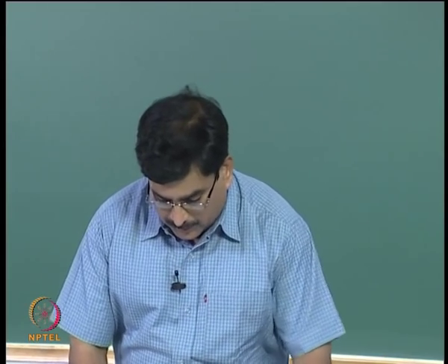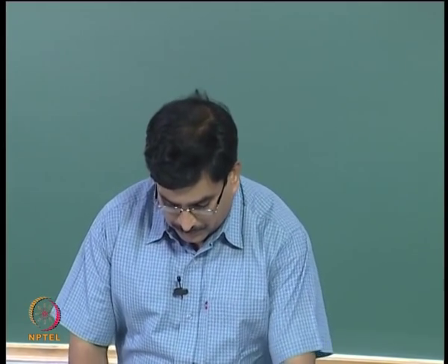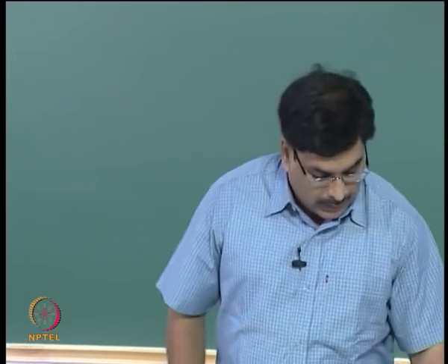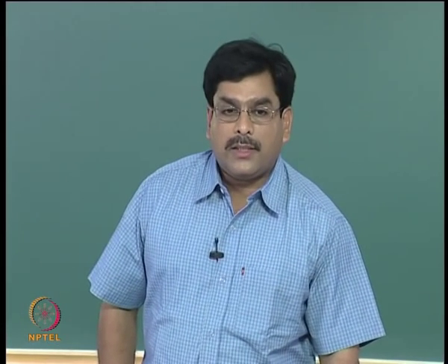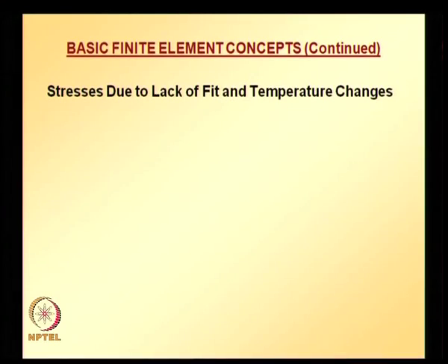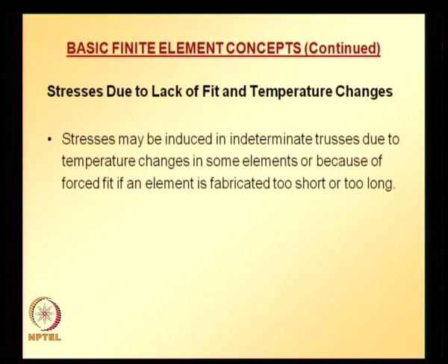So with that we will start looking at the stresses due to lack of fit and temperature changes in truss problems. Usually these stresses are induced in indeterminate trusses due to temperature changes in some elements, or because of force fit if an element is fabricated too short or too long.